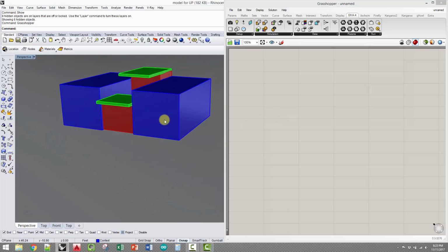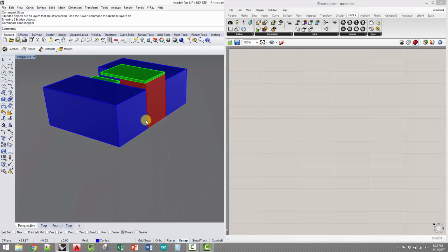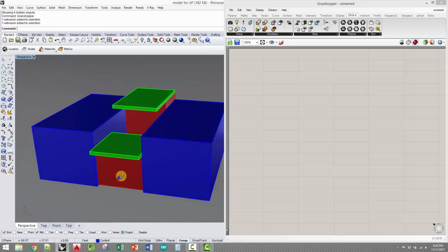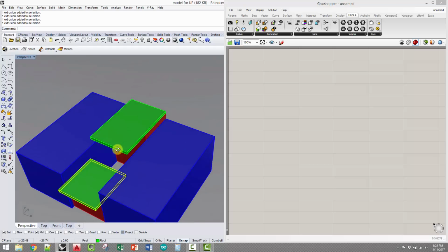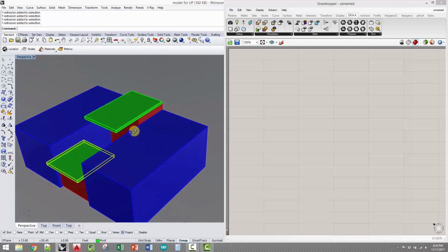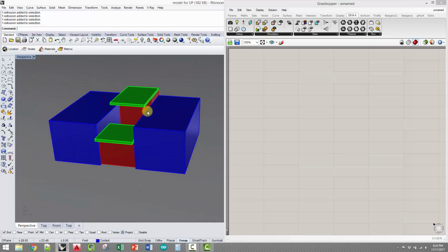And you look at this model. This is a version of the model I showed you before, but it's just very simple. It's a massing model. I've got my buildings that are next door. I've got my infill project just as massing, just as the envelope, and the overhangs and any kind of roof structure that's going to be influencing the shadows of my building. And the shadow study is going to show me where shadows are going to occur across various times of the year, so that I know where I've got light, where I've got shading, and where the neighboring buildings might generate shade on my building.